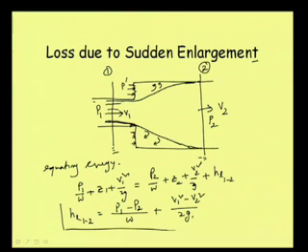So, that is what our head loss is, but of course, we need a better expression. This expression says that our head loss is the difference in pressure head plus the difference in velocity head, V1 square minus V2 square by twice g, fine.